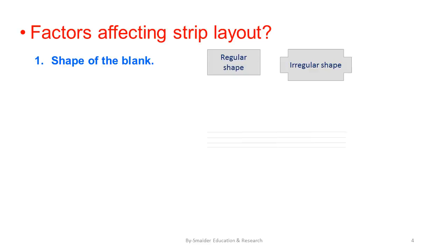In case of irregular shape, a profile where you cannot place it very easily, in that case you need to put your component in a perfect strip layout and check the effective utilization.